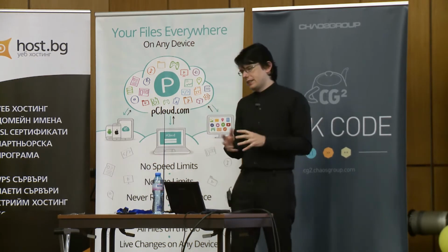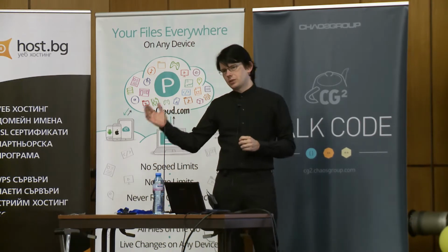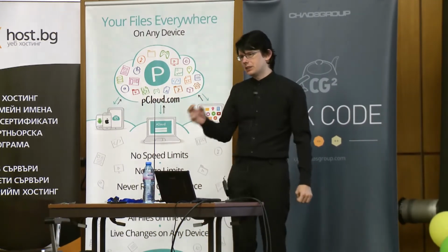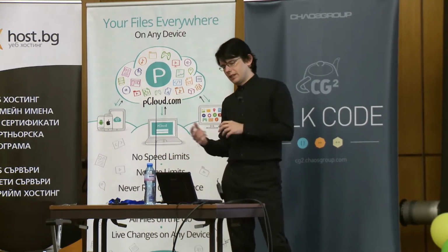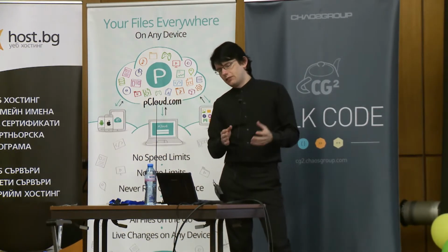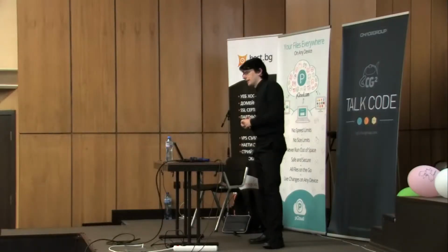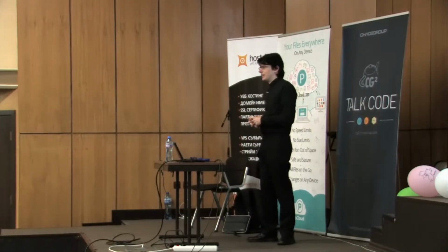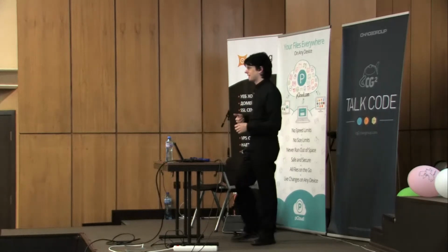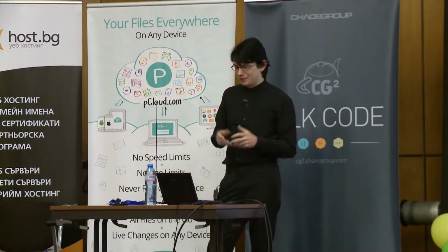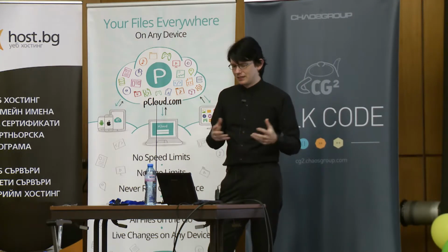The other idea is to convert not to a 0 IF, but to a very low intermediate frequency, and then sample that intermediate frequency and work with the samples on that. Whereas in the 0 IF, you convert to baseband, and then you sample the baseband data with an analog digital converter. And the ADC can never be fast enough, and it can never have enough resolution. So you want to have as much resolution and as many bits as you can get, and as high of a sample rate as you can get.